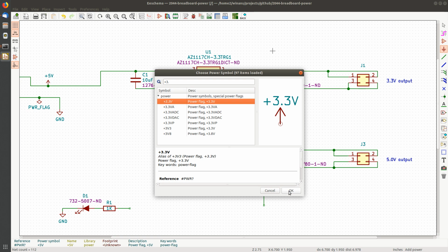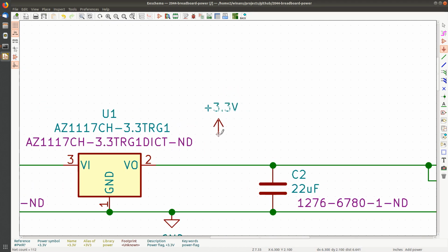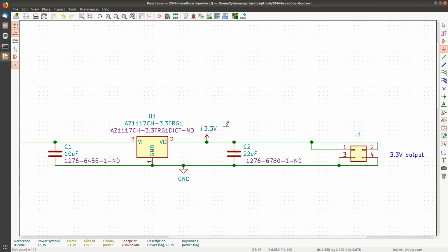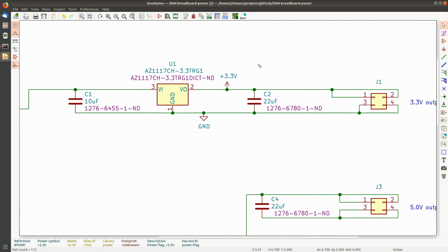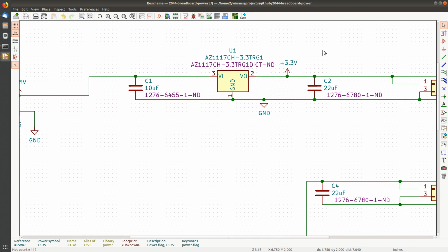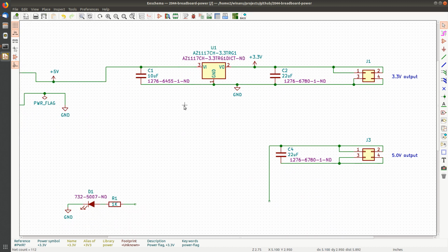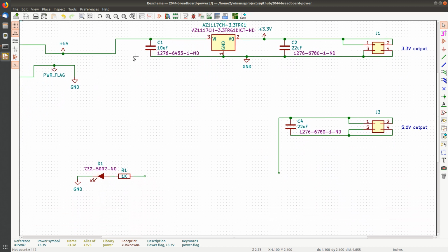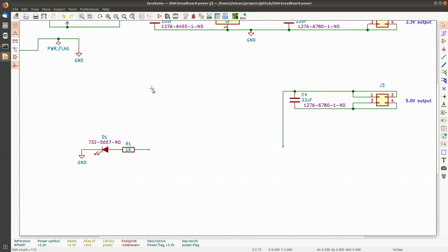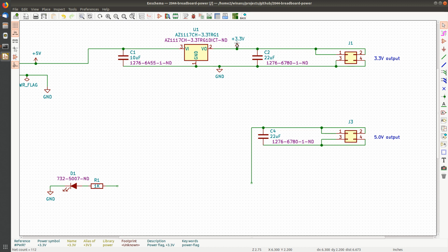Okay. And you can either call this 3V3 or 3.3V, whatever notation you want to use. All right, so now this one is known as 3.3 volts. Now, the reason I want to do this is just like the ground. I mark this as ground and that as ground. The schematic editor knows these are the same signal, even though there's not a wire drawn between the two, okay? I can now go over here and hit C to copy this, and I can put the 3V3 down there.